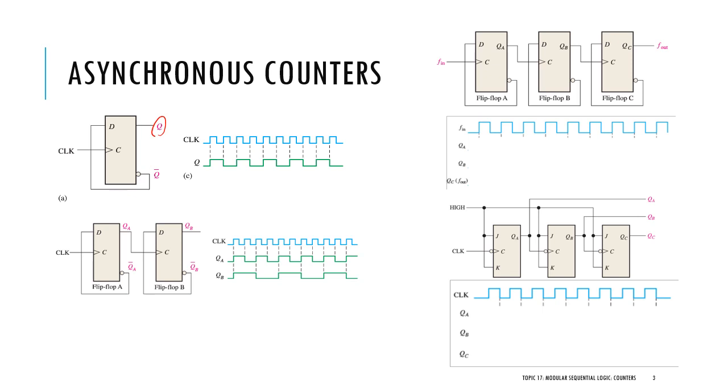Okay, so this is a rising edge D flip-flop. At every rising edge of the clock, the Q value will toggle, always changing. If we write the values 1 0 1 0 1 0 1 0 1 0, it just keeps changing, and you can think of it as counting between two numbers, 1 and 0, right? After counting down to 0, it goes back to 1 again and counts again. So this is a 1-bit